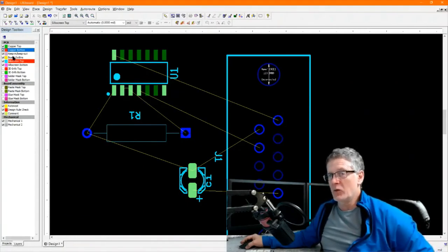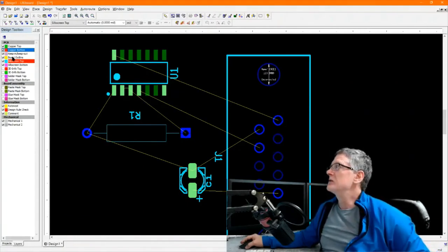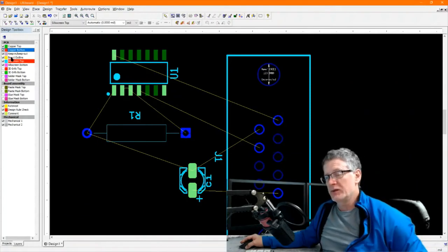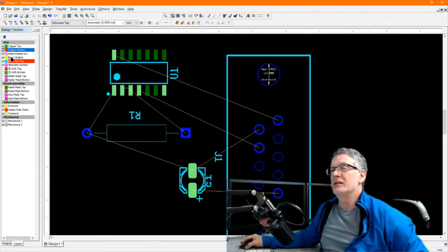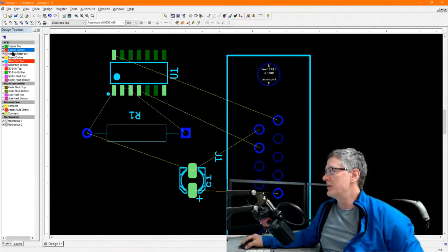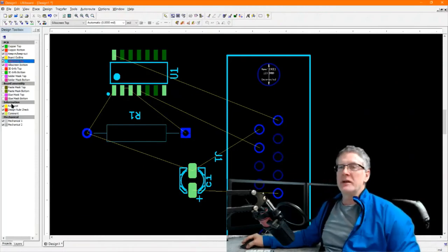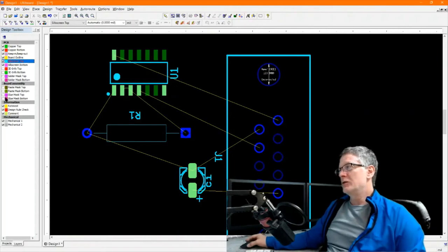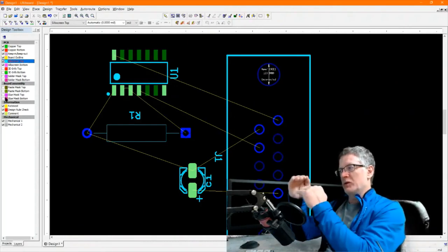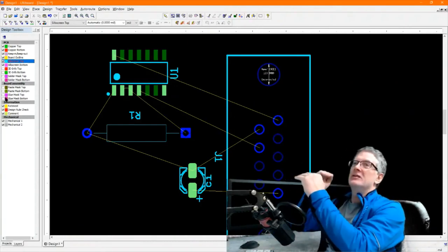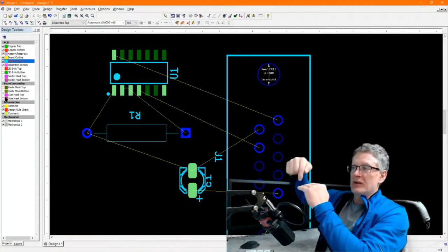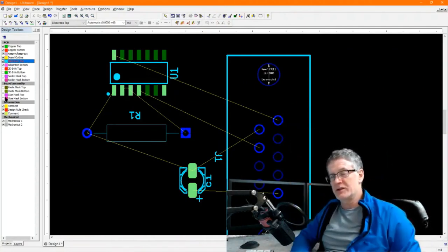Basically, it has copper only on top and bottom. You can have 4-layer circuit boards, and then they have layers in the middle of the circuit board. This is only 2-layer. So here's the copper top. Here's the copper bottom. There's silk screen top, 3D info. So there's a whole bunch of layers here that you're looking at basically. So the circuit board has layers stacked up, and you're looking at information from the top side down through the top layer from one side.